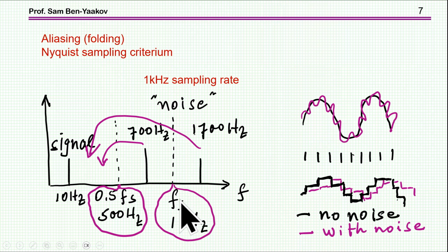So what really happens is if you have frequencies, say between 0.5 and the Nyquist frequency, let's say 700 hertz in our case, there'll be folding and you'll get a signal here in this region. So it's going back into your area, which is very bad because you cannot get rid of it by digital filtering anymore. Because once it is here, then it's part of this frequency range, and you cannot filter it out because this is the area you're working at. Okay, so this is very bad.